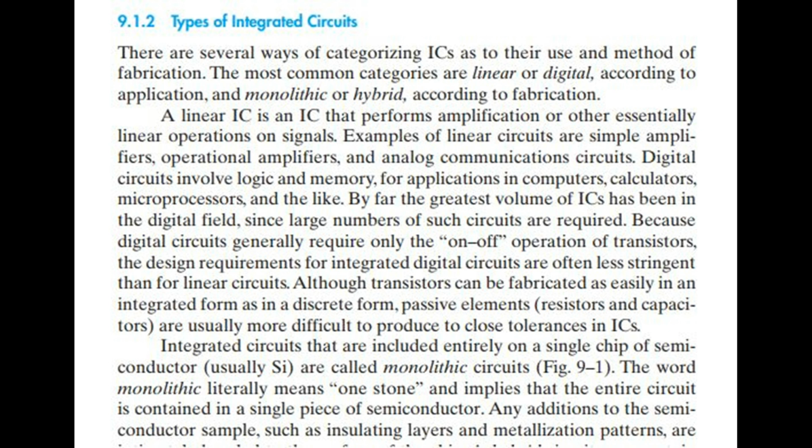By far the greatest volume of integrated circuits has been in the digital field, since large numbers of such circuits are required. Because digital circuits generally require only the on-off operation of transistors, the design requirements for integrated digital circuits are often less stringent than for linear circuits. Although transistors can be fabricated as easily in an integrated form as in a discrete form, passive elements, resistors and capacitors, are usually more difficult to produce to close tolerances in integrated circuits.